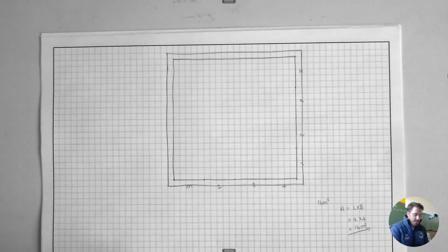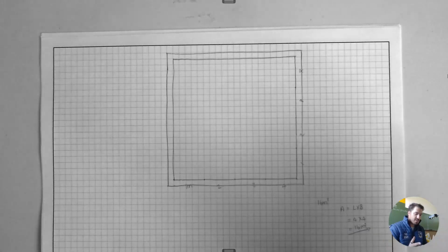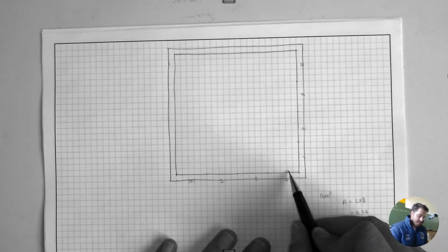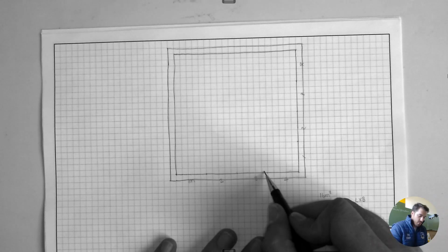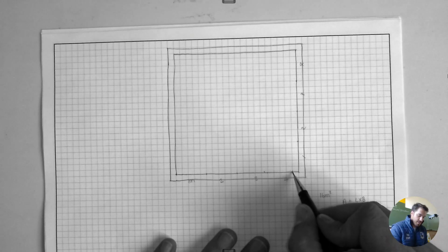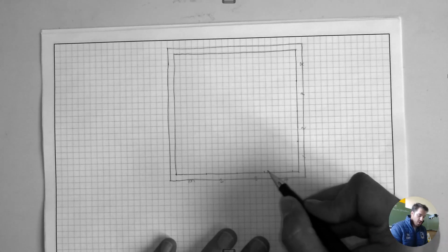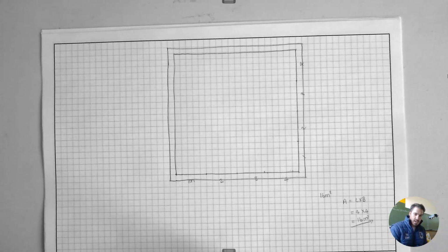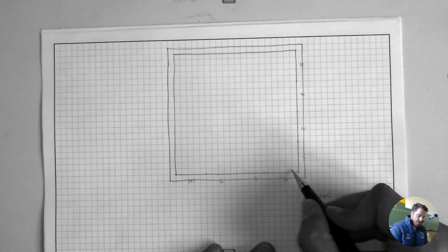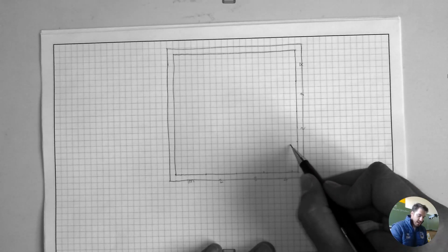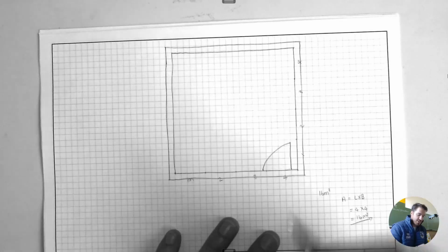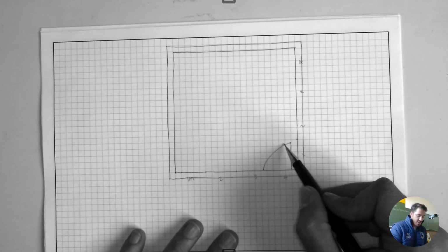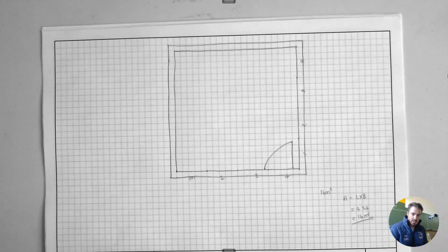So we all know that the standard measurement for a door opening in real life is 900 millimeters. So if you look at this opening, let's say from here, that's 200. So 2, 4, 6, 8. And then in between this, it's 9. So there to there. And then a door, if it opens, it obviously opens in the same width as what the opening is. So here it's going to be 2, 4, 6, 8, 9. So you want to try and draw this as closely resembling the scale as you can. So remember, this has to be going out a bit more, but this is supposed to be freehand. So this is what needs to happen ultimately once you are done.